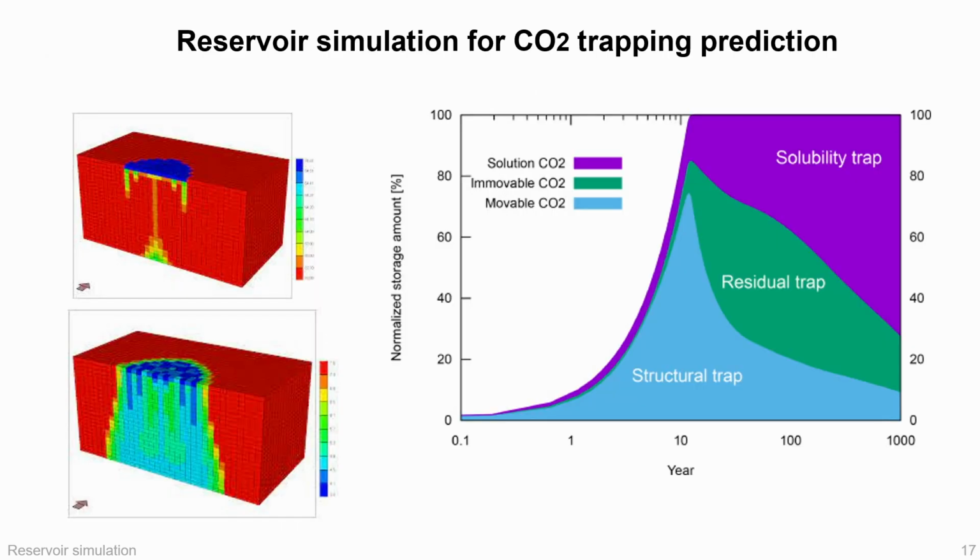This slide broadens the application of reservoir simulation beyond traditional oil and gas production. Reservoir simulation is also essential for CO2 storage projects. In that context, the simulator helps predict plume migration, pressure buildup, structural and residual trapping, dissolution, and long-term containment. This is especially relevant today because petroleum engineering is increasingly connected with carbon capture and storage. The same simulation principles used in hydrocarbon reservoirs are now supporting climate and energy transition applications.